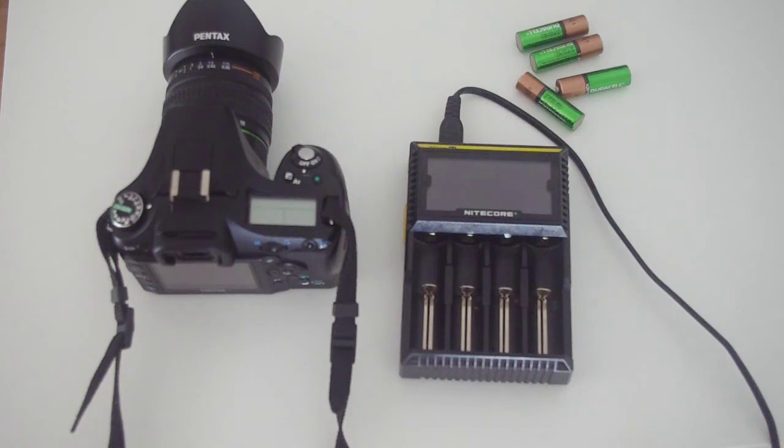Use a charger with current equal to or less than 10% of capacity. For example, for 2000 milliamp hours your charging current should be 200 milliamps or less. So do these deep discharge cycles at least 2 times per year, use a low charger, and you'll be fine.